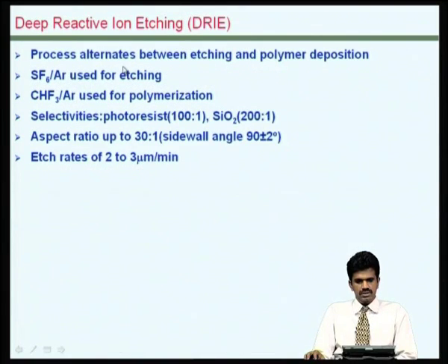As I mentioned, in this we can use various combinations of gases for etching various materials, yet we also use a step in which the side walls are coated with a kind of non-stick polymeric surface. It may go away after some time. So, these removal and attachment processes are cycled so that high aspect ratio structures are possible.